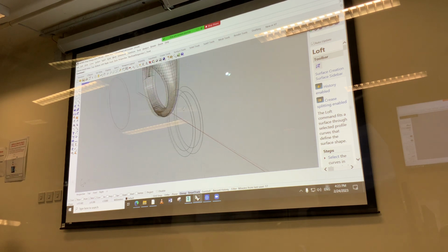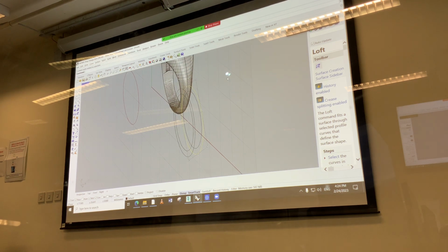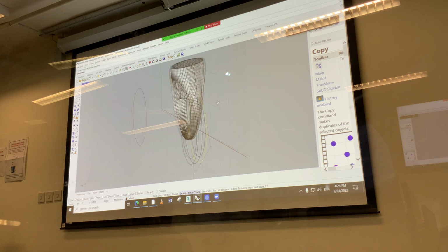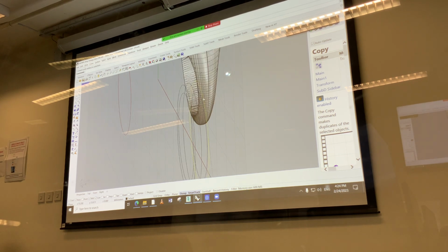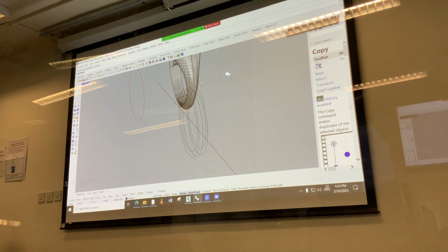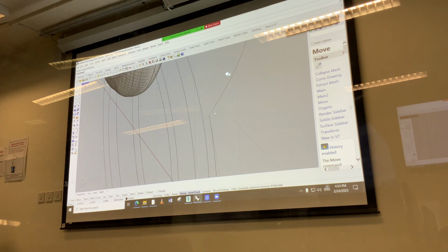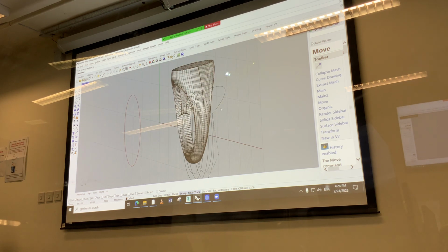Okay. Now what could I do with this further? Now if I copy this, for instance, vertical, to let's say here, and I could take my second part here. And now I want to rebuild this because this was done as a circle. So circles are notoriously problematic, and I'll show you why. Because see, when I move this control point to the back, there's a kink here, because that is where the circle closed itself, because it's still in Rhino seen as a circle. And unless you like to have this kink and not a continuity, I would not recommend that.